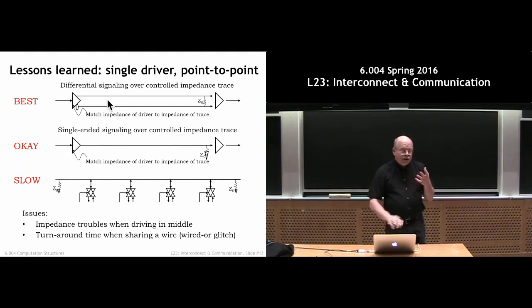So differentially, if you're looking at the difference between the two wires, even severe electrical disturbances have no net effect. And you can say, well, it looks like there could be a loop here. Maybe I'm capturing a magnetic field. So these are usually twisted pairs. In other words, the two wires are mechanically twisted together to make a braid that is pretty impervious to almost all sorts of electrical interference. In controlled environments, what's called single-ended signaling will often work, because doing these differential pairs is a bit of a pain from the point of view of laying out your PC board.